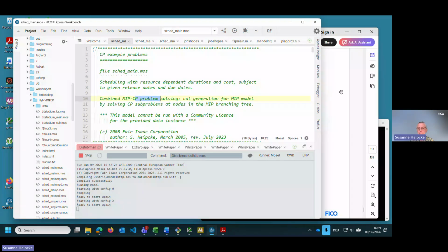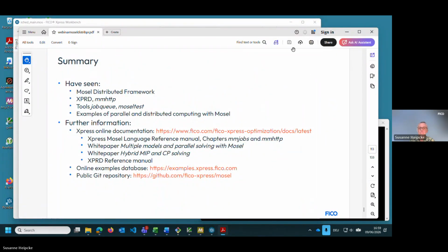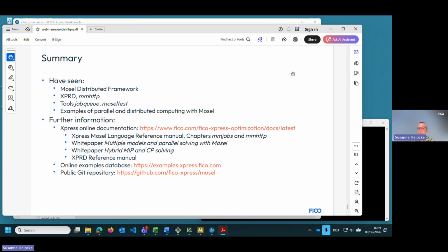Thanks, Suzanne. And last question, on the shared memory for problems, we were previously recommended to communicate via files rather than memory for performance. Is this still the recommended approach? It depends on your systems. The shared memory is memory. It's information that sits in memory, and then this memory is not available for your solving. So if you have large memory blocks, and this is why we've recently introduced this inspection functionality for shared memory, if you store a large amount of data in shared memory, this is space that is not available to the solver. So if this becomes really large, better store it in files to free space for the solving. Or there's also the FTD that I've shown. Once you don't need the shared memory block anymore, delete it, perhaps even before you start the optimization run.